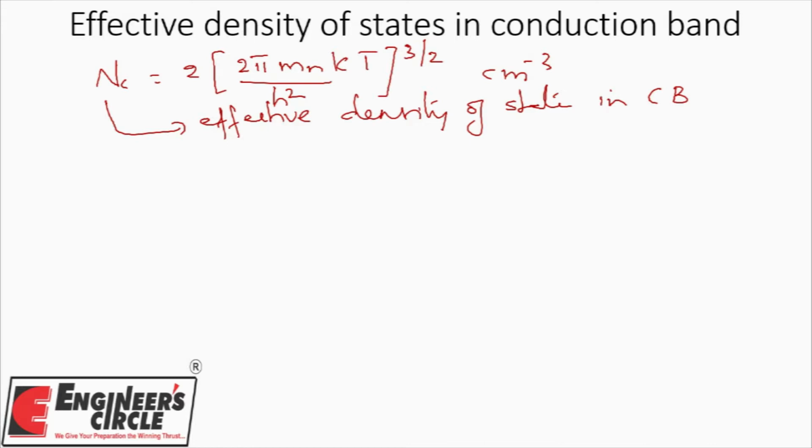This means, we take the energy distribution in electron volt. We have a conduction band edge. We know that the distribution of energy states over the energy level is non-uniform and is approximated by the parabolic density of states approximation. And finally we get the concentration of carriers. You can see that the lower energy states are filled, and when you go higher up, the energy states are empty.